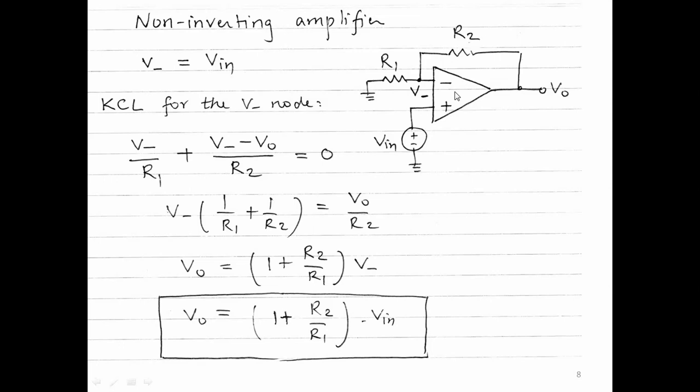So the advantage of op-amps is that I can buy a general purpose op-amp that has high R-in, low R-out and a high voltage gain, and then I can make an amplifier of whatever gain I want, depending on the application, by simply connecting two resistors R2 and R1 across it. The vast number of applications for which this chip can be used makes it very versatile.